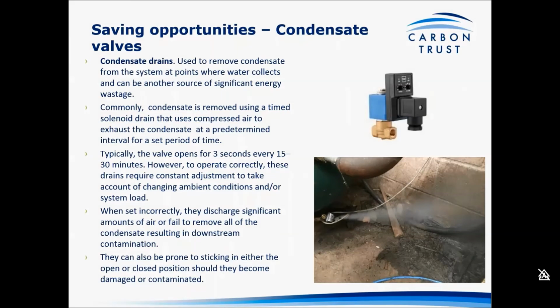Condensate valves are used to remove the water from the system that has condensed out. There's a variety of ways this can be done. It's rare to come across it now, but often there'd be just a hand valve at the bottom of the receiver, and one of the maintenance guys swings around three times a day and cracks the valve open for 10 or 20 seconds. Again, you're wasting the air that you have generated. More commonly, it would be by the timed solenoid valve, which is represented there.